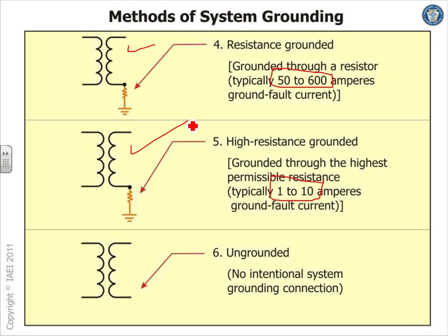Then you have a ground fault, no problem, bring it on. It doesn't trip, and if you have a transient in the voltage, the system is grounded, so it sucks all this transient and takes it to the ground. So that's that. But with this, you have to alarm. Of course, you have a monitoring system that alarms if you have a ground fault.